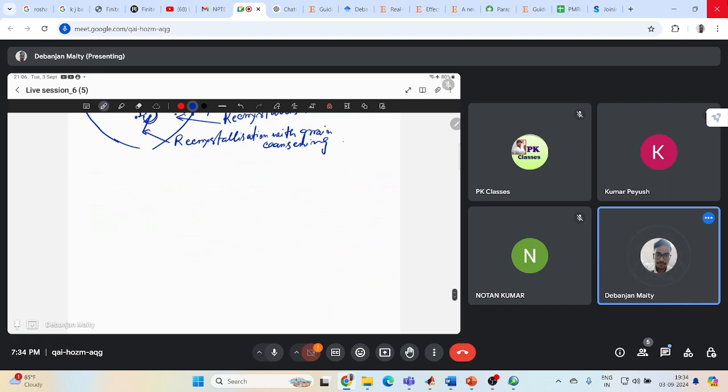The strength of your work hardened metal decreases with increased annealing temperature. So as you approach your fusion boundary, the strength and hardness of your heat affected zone will decrease. Correct, no?